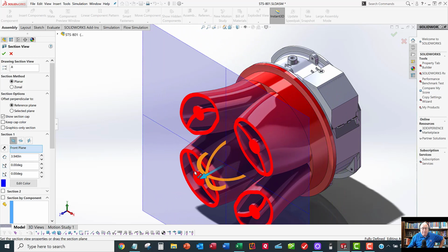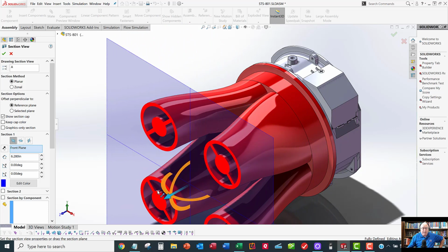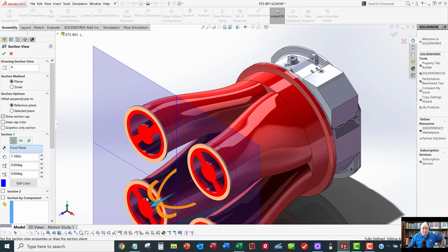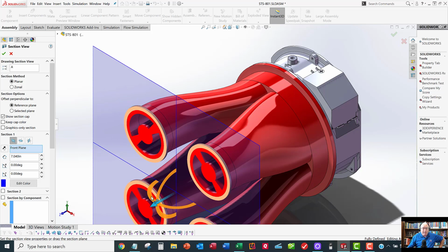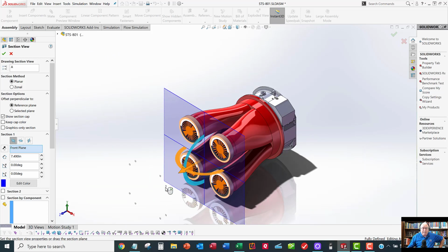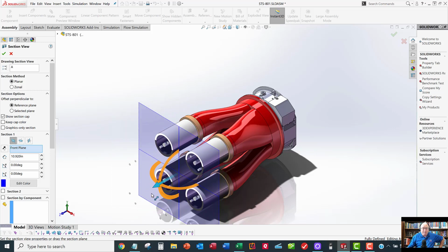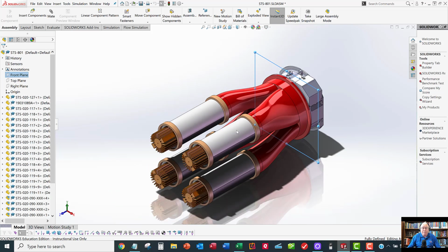It floats around and morphs itself into a shape that eventually looks just like the end of the heat sink. At that transition, all of the air is flowing right into those two voids on either side of that heat sink. And then those heat sinks just continue on with that constant cross section. There are different lengths of heat sinks and different configurations of those heat pipes, and we'll deal with those later.